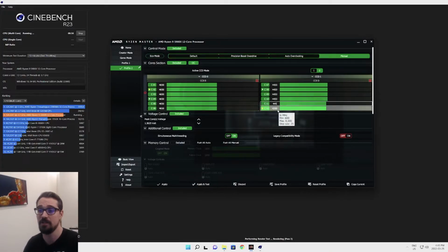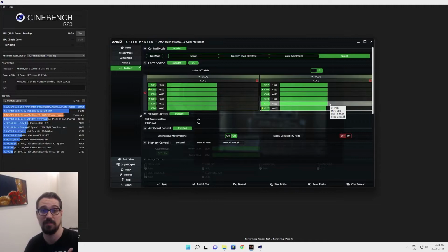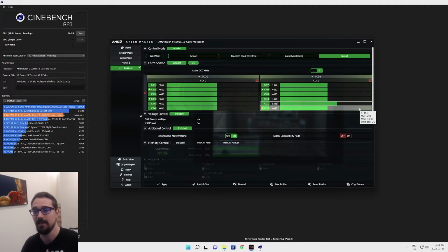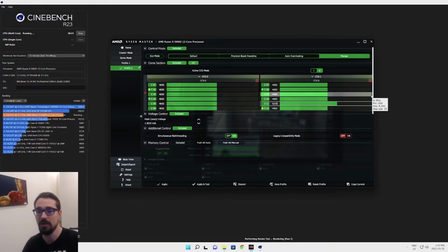But my recommendation is that if you're brand new to this, just go and unlock the power limits for your CPU. Increase your PPT, your EDC, and your TDC by 20-30% increments, and then smaller increments as you go. Just make sure your CPU is running within the thermal limits using Precision Boost, and you've got more performance out of your CPU with really no fuss, no muss.